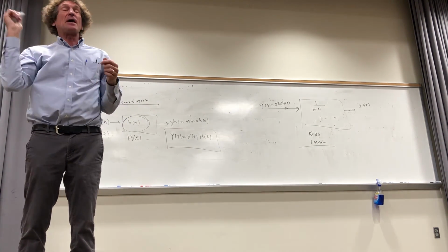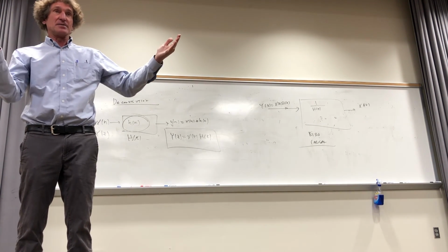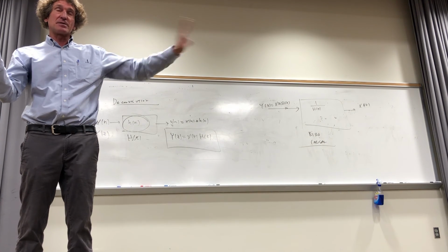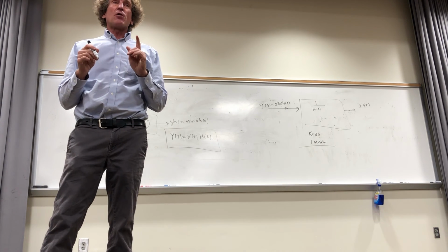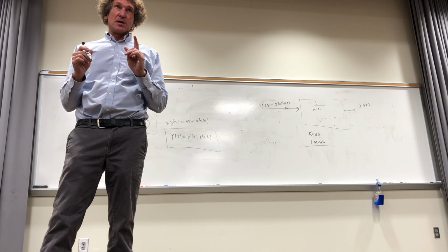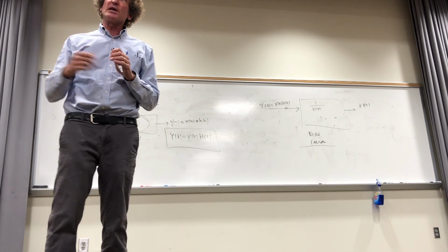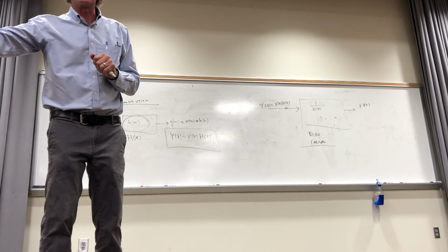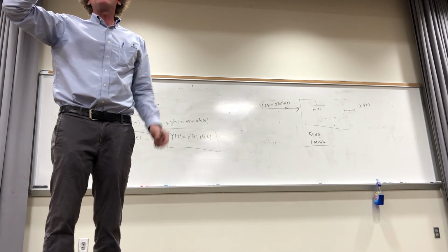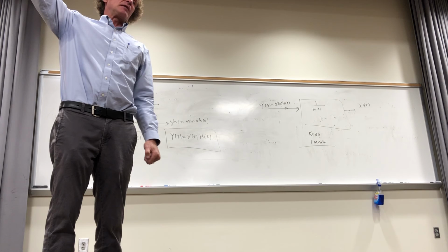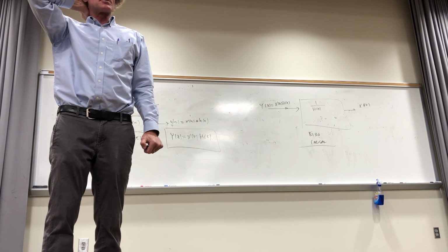Finite impulse response filters are beautiful because h of n is limited, and 0 beyond and 0 before. Those almost always work, to the best of my knowledge, when you do the inverse. But when you get unbounded ones, you get problems, because usually if one is stable, the other is not. If the poles of h are inside the unit circle, when you take 1 over h, the poles are outside. Do you follow me in this class? So you have to be real careful with infinite impulse response filters.